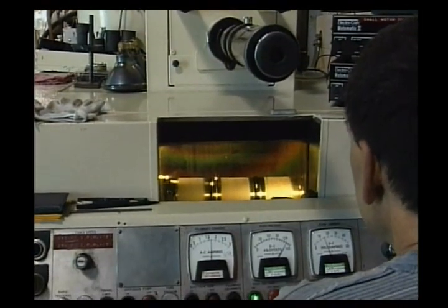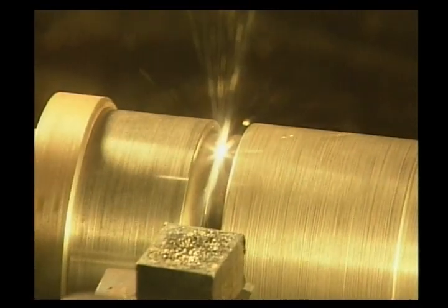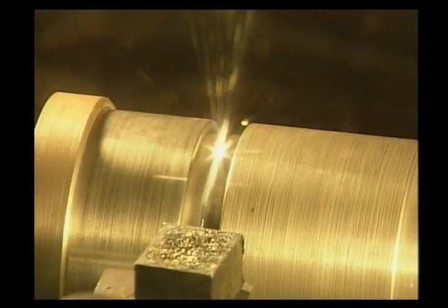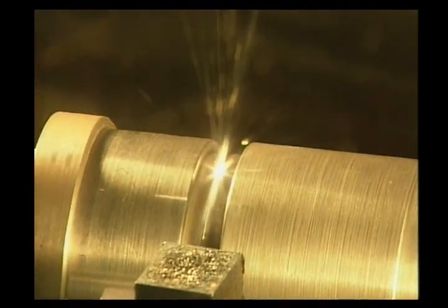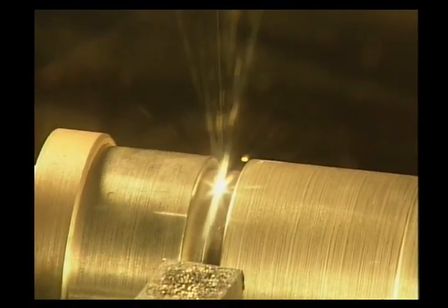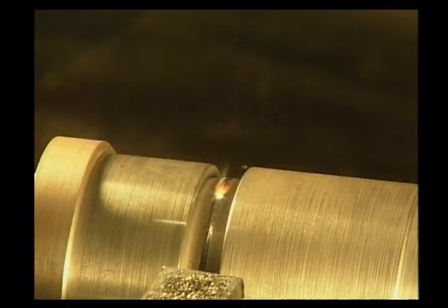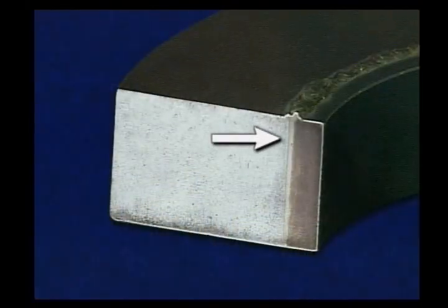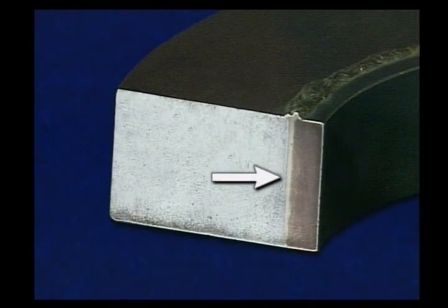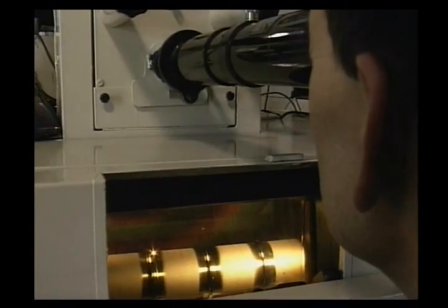This electron stream is developed in high vacuum, but actual welding can be performed in either high vacuum, partial vacuum, or standard atmospheric pressure. Because of the intense and concentrated heat generated, total heat input is low, minimizing heat-affected zone size and part distortion. This also allows for the creation of extremely deep and narrow welds. Additionally, joints inaccessible by other welding processes can be welded.